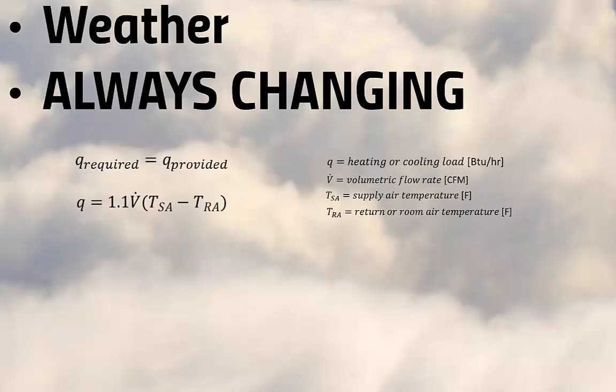TSA is the temperature of the supply air being delivered to the space in degrees Fahrenheit, and TRA is the temperature of the return air being sucked out of the space. TRA can also be thought of as the room air temperature, because as we discussed in the last lesson, the room air and return air temperatures are assumed to be equal.